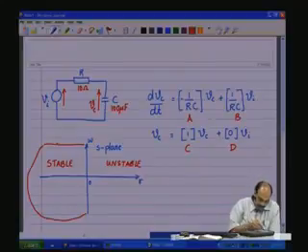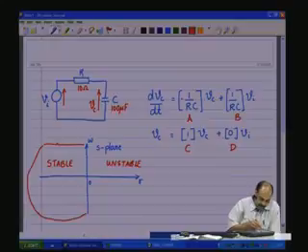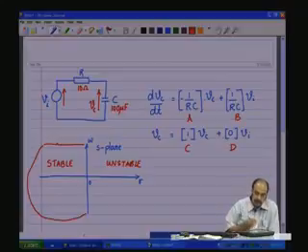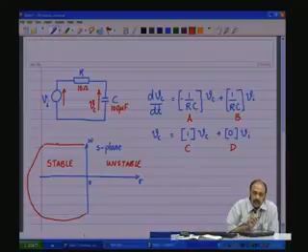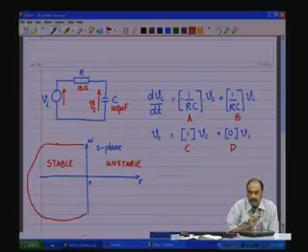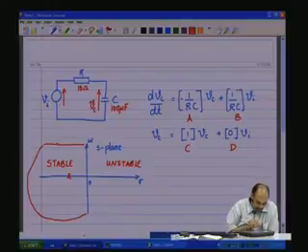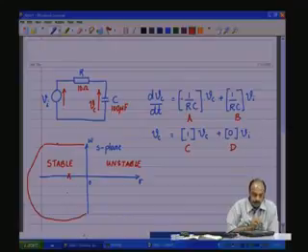And we probably will get most of the time a plot of the complex plane corresponding to the left half of the S plane. Now, let us see what are the things that will be plotted. One thing that you should note is that this is a system which has only one state variable, one differential equation, and therefore, there is only one root to the characteristic equation or one eigenvalue, and therefore, there will be only one pole, and that one pole will be on the real axis, because if you have a complex pole, then you have to have a mirror image also.